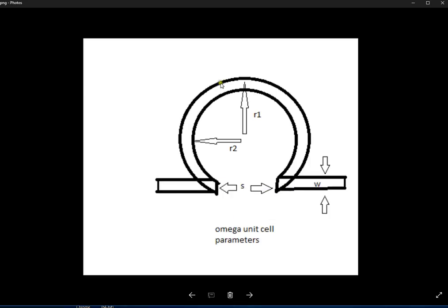First you have to draw the bigger one, the big circle having radius r1, then you have to draw another circle with radius r2, then you have to subtract the first cylinder from the second cylinder, so you will get a ring, and then you have to make a slab here and subtract it, you will get a split here. So select this midpoint, then design a brick here, select this midpoint and design a brick here. The designing procedure is the same if you have gone through those videos, or if you know the basics of designing things. So this is easy. I will give you those parameters, and the paper has them also. So this is the basic.